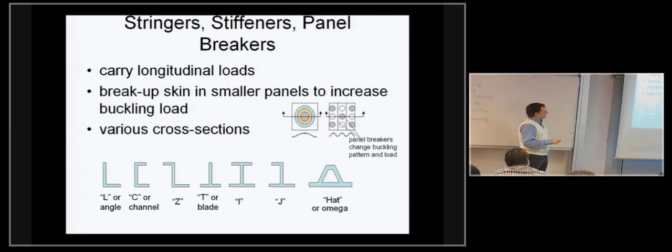If I add stiffeners, and those stiffeners, which are meant to be those vertical lines shown here, are stiff enough, they actually will stay straight when the skin buckles, and the skin will only buckle in between the stiffeners. Those little gray and white circles are meant to be positive and negative half waves coming towards us or going away from us.